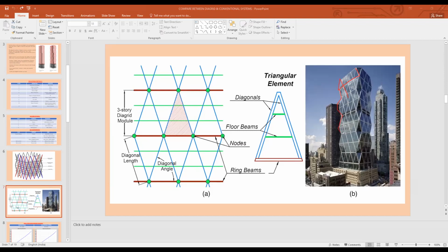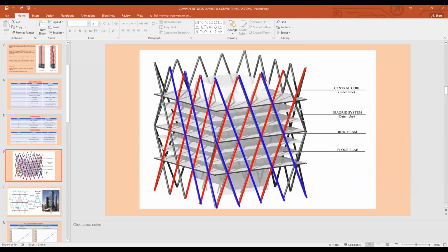Right. So how can you fix the glass frame here? Generally, I think the glass is on the outer line. Yes, glass is fixed on aluminum framing, and aluminum is fixed to the main framing, either steel or concrete, by means of brackets. Okay. So here if we have to fix that, we can fix the glasses on their outer periphery, right? Like on this one.